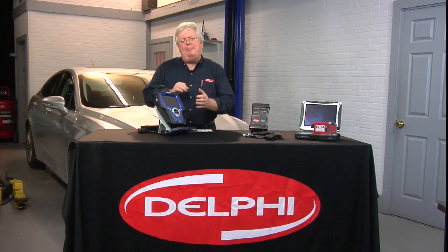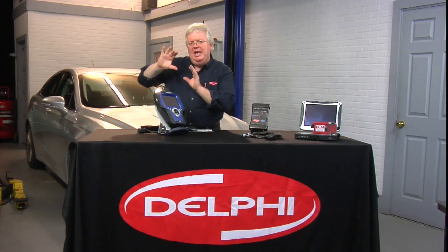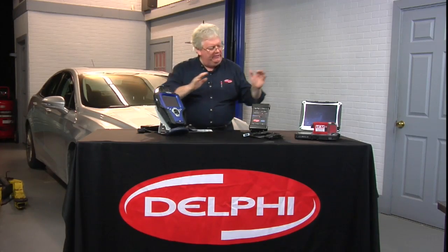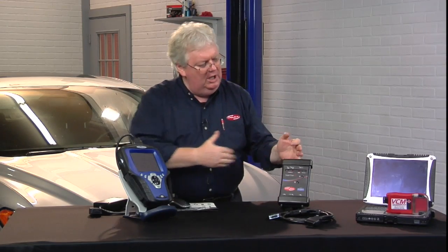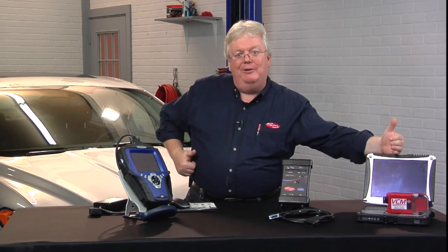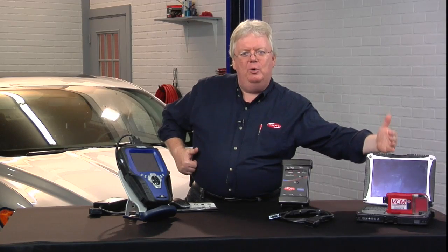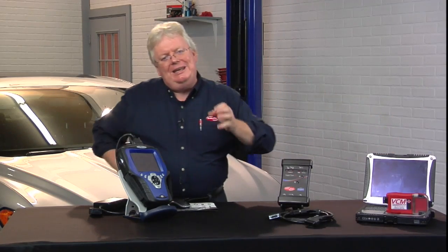The difference you get into is when you step up and you address mode 6 with these OE level tools, or of course the factory tool like the IDS, you go into enhanced powertrain in this tool or that tool. Or you'll be in enhanced powertrain pretty much from the get-go when you go into a factory tool. When you're in enhanced, those TIDs and SIDs will be the SIDs, the second column, which is the specific part of the monitor that's ran.